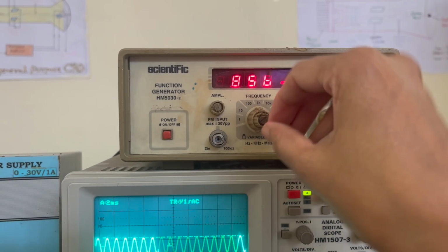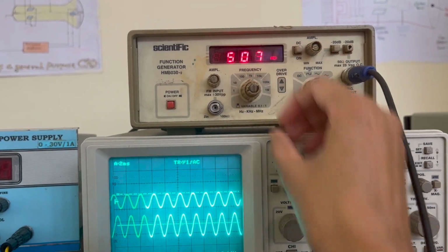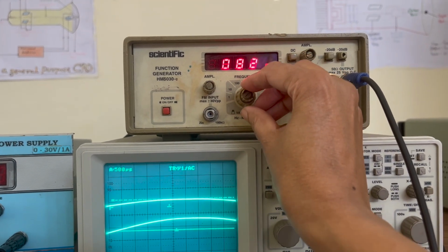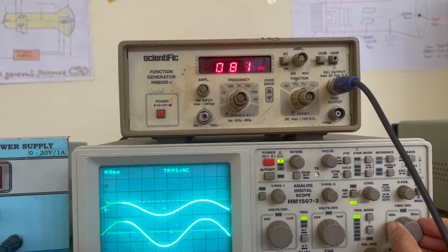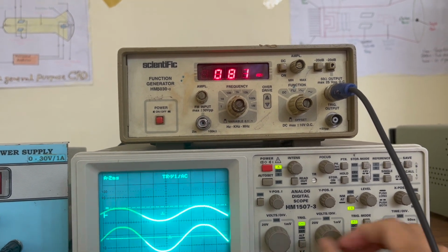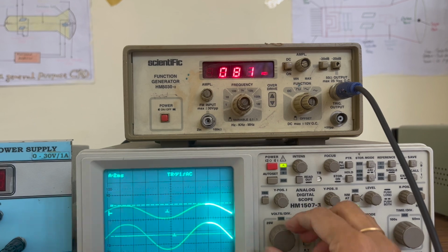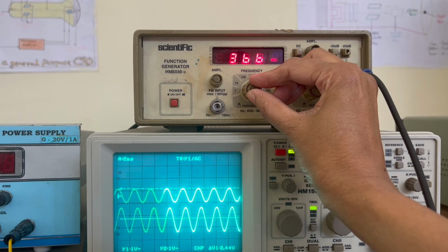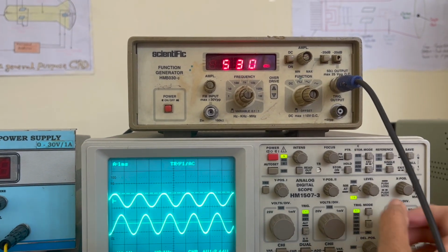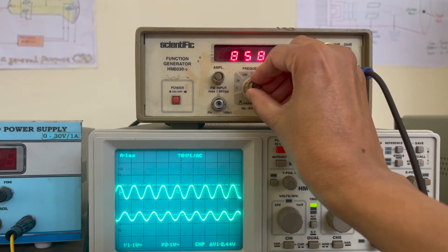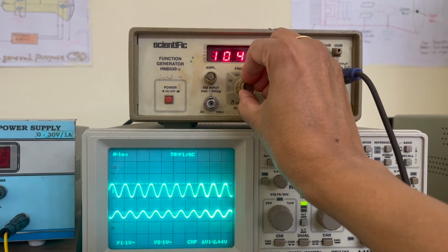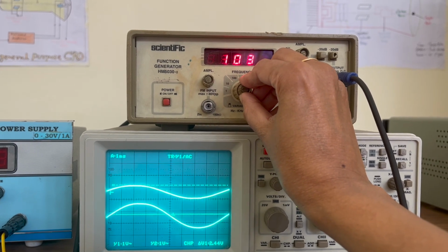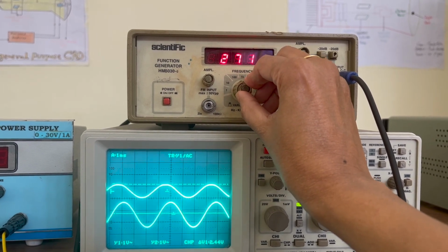This is the output of the 2nd order filter. It is a low pass filter, right? It will pass low frequencies and it will attenuate high frequencies. So we have a frequency of 80 Hz, and the output amplitude is greater than the input amplitude, as you can observe. Now go on increasing the frequency: 120, 200 Hz, 400 Hz, 500 Hz, 600 Hz, 800, 1 point, and 1.2 kilohertz, the amplitude becomes smaller. So, the cutoff is around 1.2 kilohertz, as you can observe, right.